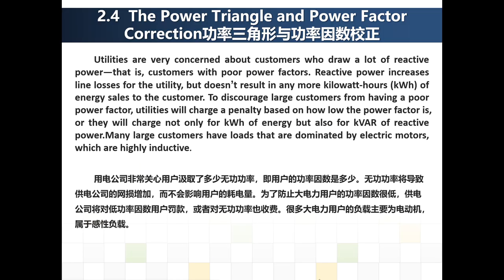Utilities are very concerned about customers who draw a lot of reactive power, because reactive power increases line losses for the utility, but does not result in any more kilowatt hours of energy which we sell to the customers. So the utility will not receive revenue by delivering reactive power.